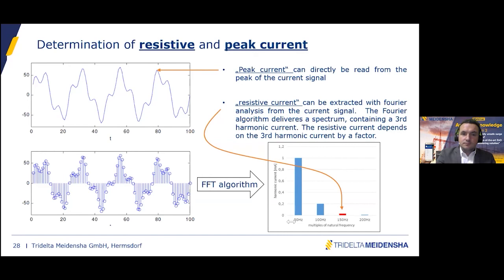And our studies came to an end when we talk about surge arresters that are placed in warm regions, where the outside temperature normally is the same as the inside temperature, or where the sunlight greatly affects the measurement, because the surge arrestor housing takes on a very high temperature that's even higher than the core, than the zinc oxide of the surge arrestor, which makes it hard to define what's good and what's bad.